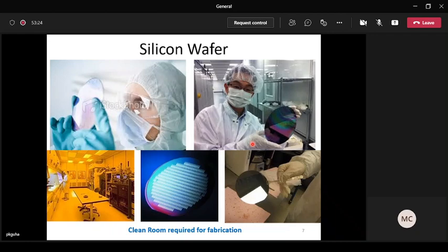This lithography process usually takes place in a yellow room, because white light often interacts with photoresist and changes its property. So you need to do lithography in a yellow room, and the entire fabrication process is usually done in a clean room. By clean room I mean there will be fewer particles in that room, because your devices are maybe a few tens of nanometers, which is of the order of the size of a dust particle.